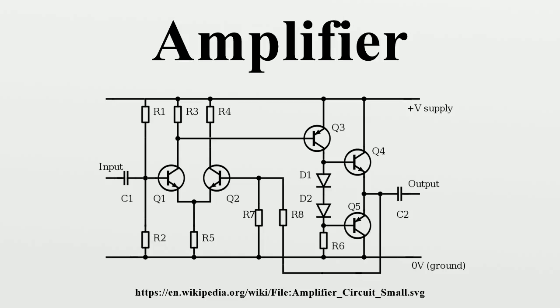Operational amplifiers. An operational amplifier is an amplifier circuit with very high open-loop gain and differential inputs that employs external feedback to control its transfer function, or gain. Though the term today commonly applies to integrated circuits, the original operational amplifier design used valves, and later designs used discrete transistor circuits.